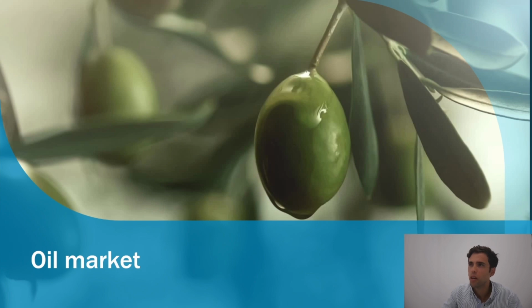The olive, for example, could be extra virgin olive oil, where we need to cool it to 15-18 degrees in stainless steel tanks to preserve its properties. Or even sunflower oil, where we need to maintain temperature control to prevent rancidity and the formation of unwanted waxes.